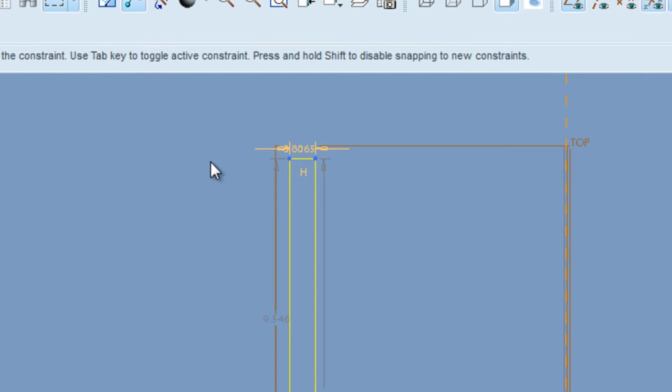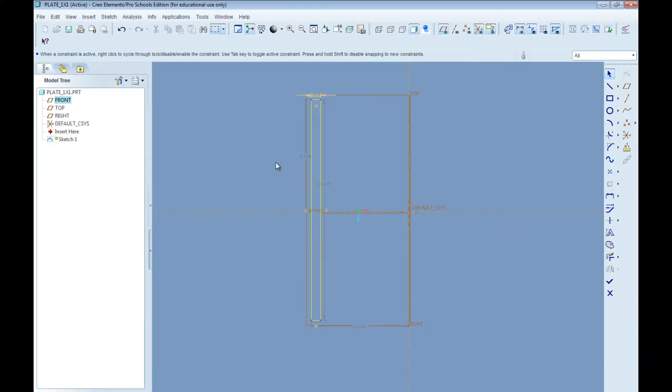Now we want to create a square from this. Instead of having to go down to this dimension and typing the same thing, because we want this to always be a square, we can set a constraint. A constraint basically constrains entities to, let's say, lines or being equal.